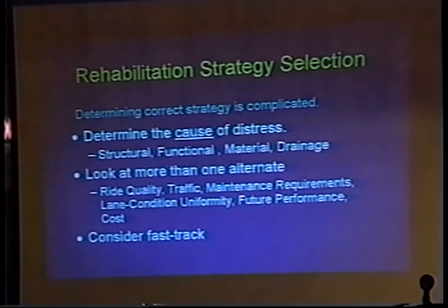The maturity meter was used in an unbonded concrete overlay application up in Cleveland in the downtown square there, where they had a concrete base and they wanted to beef up those bus pad areas where the bus stops were.